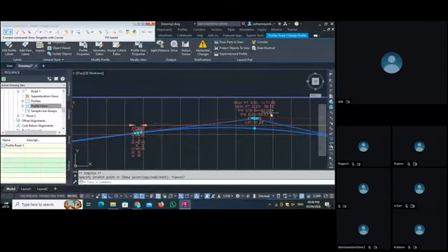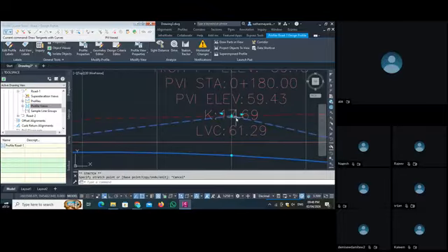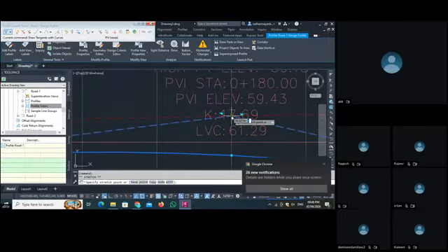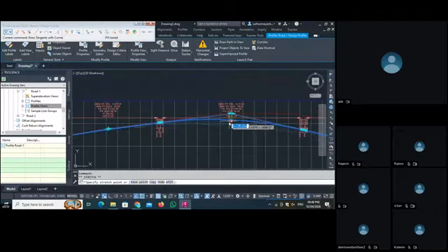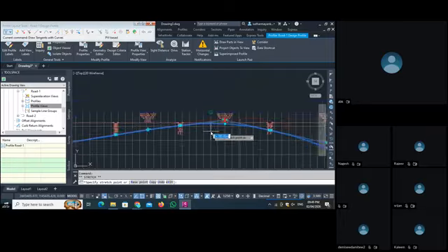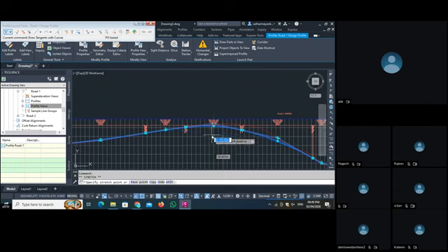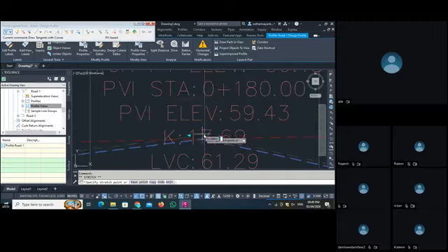See the line, see the changes. The second thing, for this curve, if I select this one, you can minimize or maximize your curve. But the first entity where we started and the second entity where we ended, these two points remain fixed. Only our curve is manageable with this triangular grip.